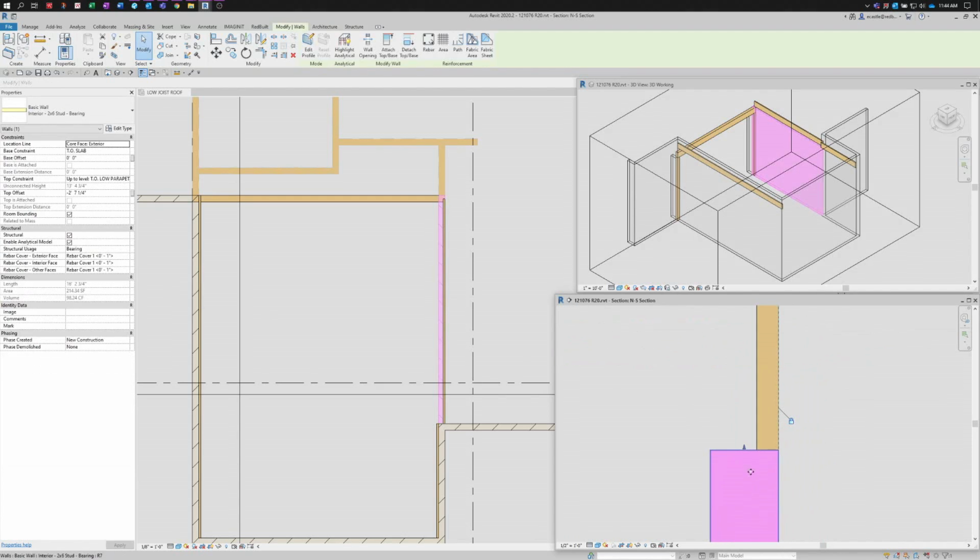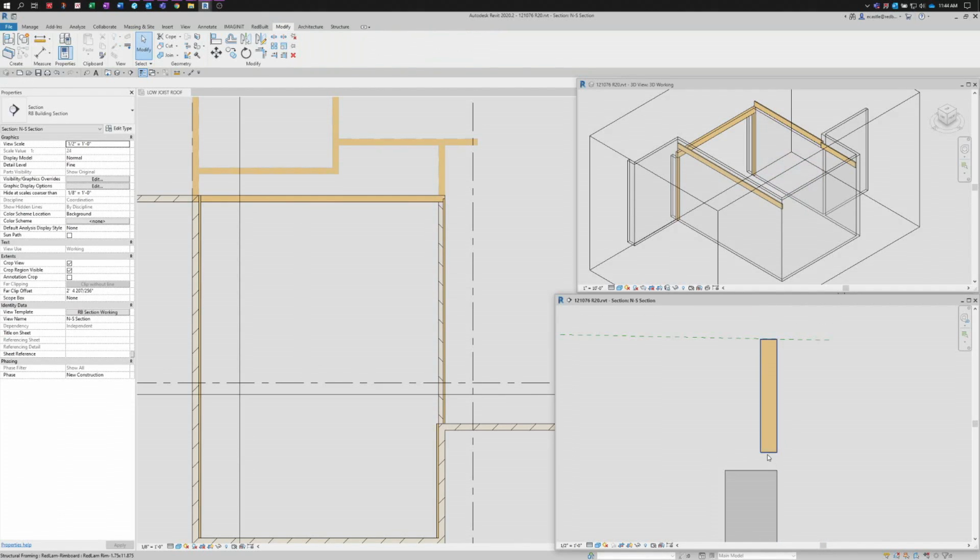Also, sometimes if your wall is not set to be flush, you can easily use the align tool and align the wall to here. You can lock it so if you change the depth of your rim, the wall will change with it. In this case, we will not bother with that.